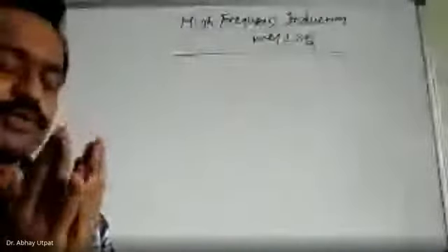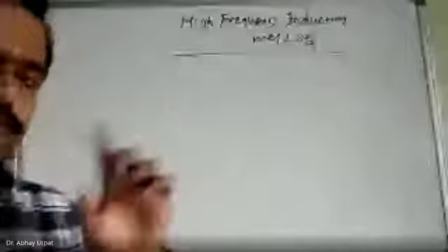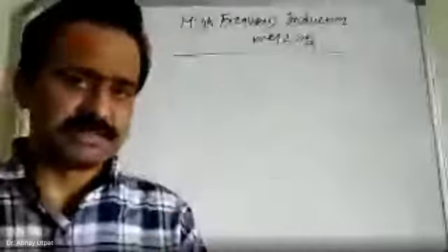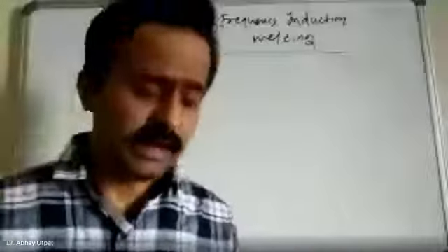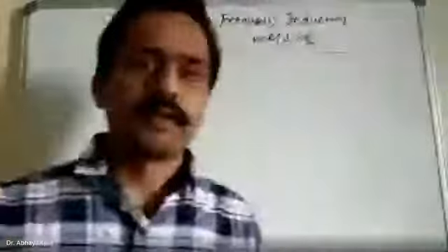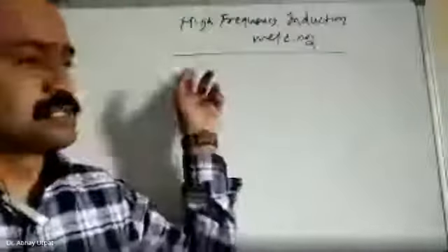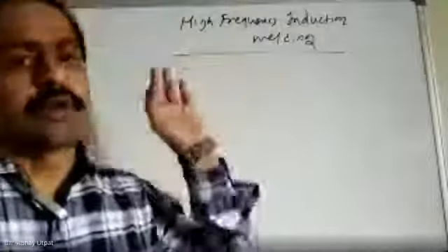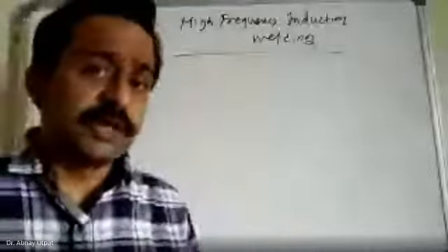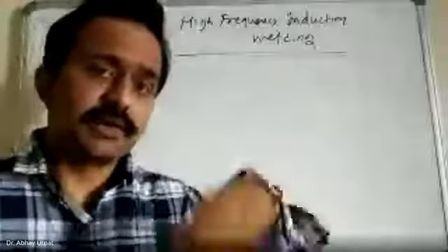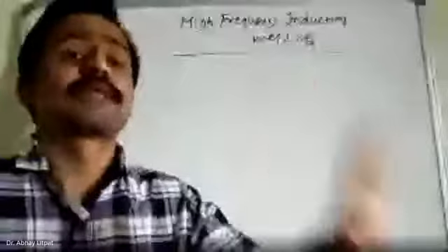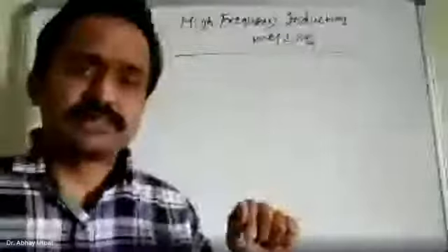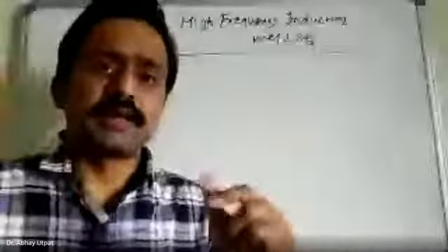So depending on that, you can replace this with another concept. These are called implants. First thing you remember: this technique is used for complicated joints. When the joint is complicated, your metallic part and your coil, everything will become complicated. So in the case of complicated joints, it is very difficult to place the insert metallic part between the mating surfaces.